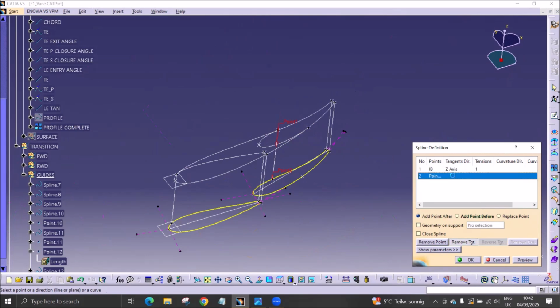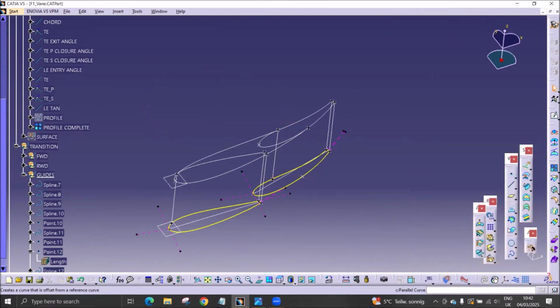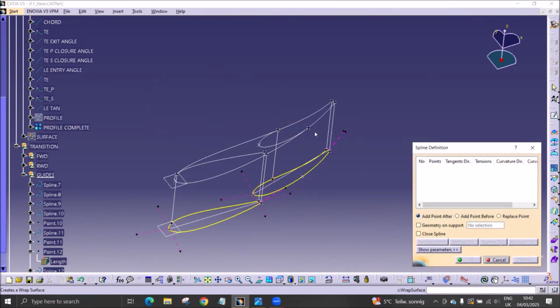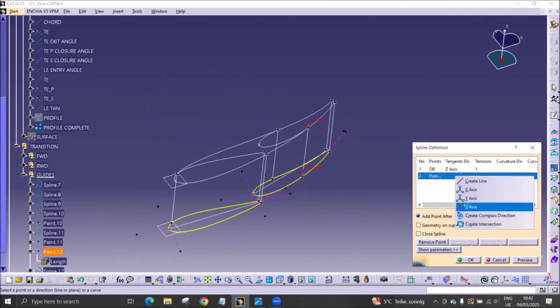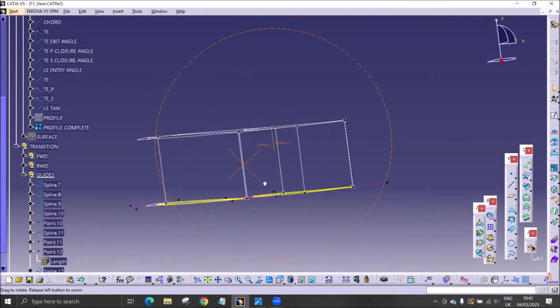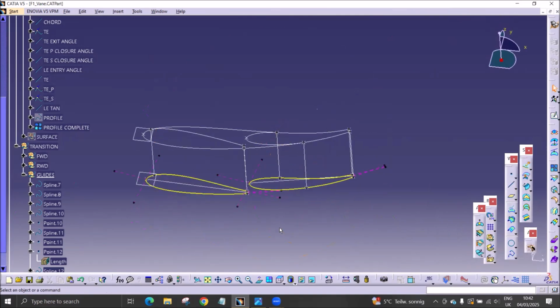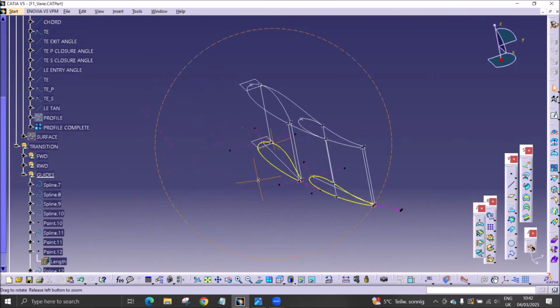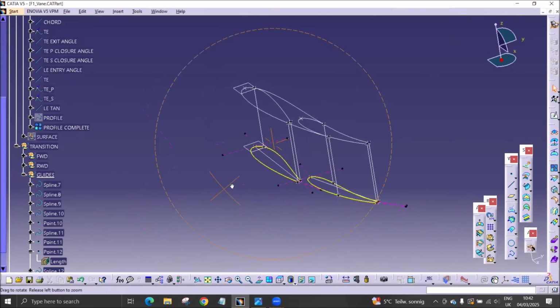Okay, give it a tangency direction, reverse the tangency direction. Okay, so you can see where this is going. So we are basically splitting the surfaces that will be tangent later on, and for ones which will not be tangent later on. So we can build the forward element with 3 surfaces and the rearward element with 4 surfaces. And you can see how this works in a bit.